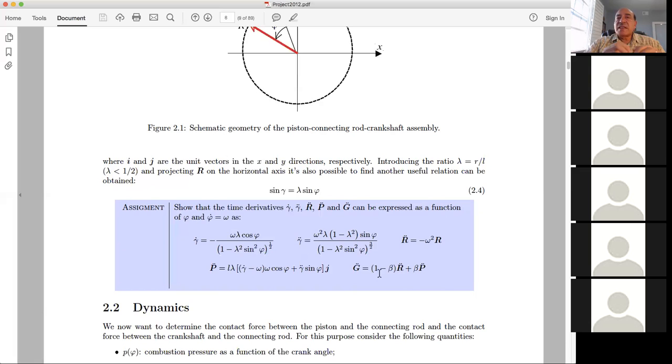But if you use it, you just have to know what it means, and figure out the relationship between that pressure, at least the peak, and the pressure that would be relevant to the engine that you chose, because every engine has a different pressure. The higher the pressure, obviously, the stronger the connecting rod has to be, and the bigger.